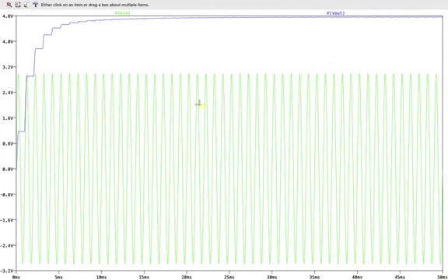So if you see here, this is my V in, where as I mentioned, it's 6 volt peak to peak. It's going from this peak to peak. You can see that the output voltage has ramped up and has gone almost, not exactly double, but to a value of around 4.8 volt. It is supposed to be 6 volt because 3 volt is my VM. According to theory, it is supposed to be 6 volt.